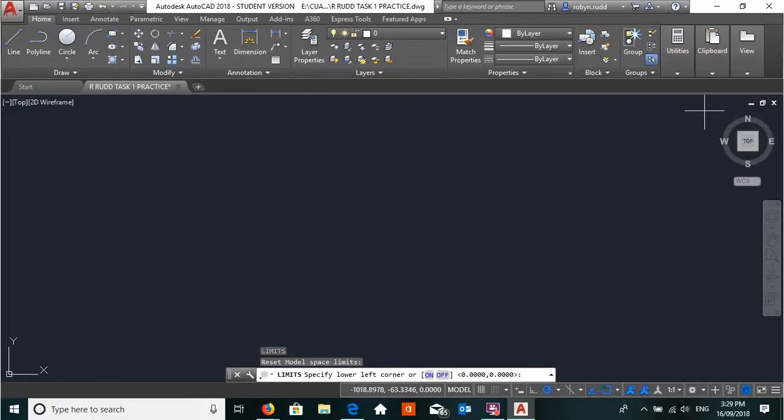And then I want to be able to create this invisible rectangular area up there somewhere. So I've identified my first lower left corner, which is 0,0, so I press enter, and then I'm going to give it a maximum up here in the upper right hand corner. You can make anything up because it's a small drawing at the moment, but generally just think of how big your area is. So if you're drawing 7,000, ultimately you want to look at maybe